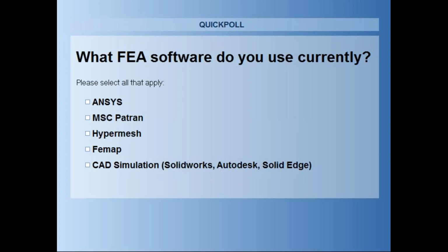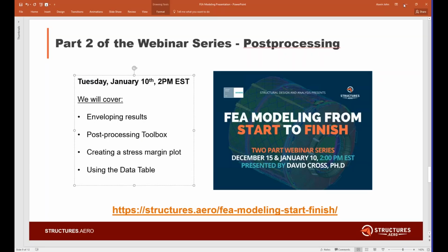Yes, so someone asked a little bit about, is the C-bush connector available to the viewers? And yes, it is. So you can view C-bushes and all the details about it right there in the Femap window. And I'm guessing you saw that once I created the C-bushes here. So you can see the C-bush connection in the viewer. And then another question was, how would we represent this bond?